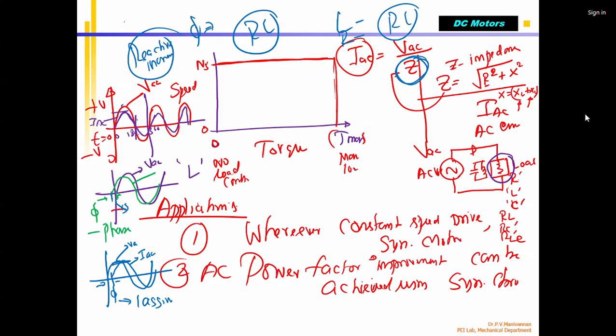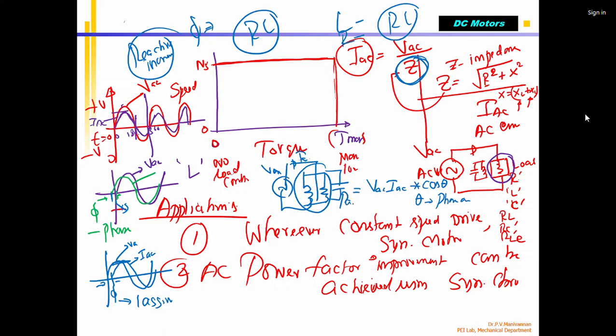So if you have an inductive load motor, what they do is, I have a coil which is represented by inductance and resistance together, and I add one capacitor. Correct? This is my actual load connected to AC power. A voltage is applied, IAC is flowing. Because of it, there's a phase angle, and reactive power comes into it. We say that PAC equals VAC multiplied by IAC multiplied by cos theta, where theta is called the phase angle. So this is the power.